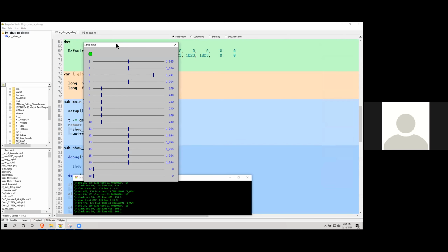All right, so now it seems better behaved. The receivers are set up so that... I'll try to keep this near the microphone, so you'll hear the switch go off. You notice it was kind of a 2-step process. The LED went red, so that's the loss of frame or loss of signal bit in the error channel and that flags byte. And then after, I think what happens is it decides, okay, it's not coming back, so we're going to go to fail safe mode.